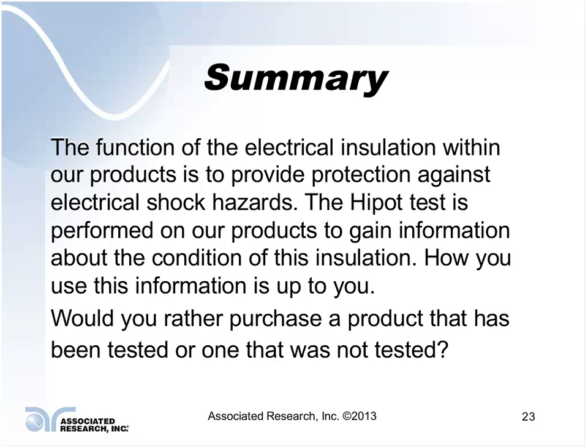Also, if you're monitoring the current while ramping up the test potential, and all of a sudden you see a nonlinear increase in your leakage current, where it starts to rise much higher than what it was, it may help you predict when a failure is going to occur.